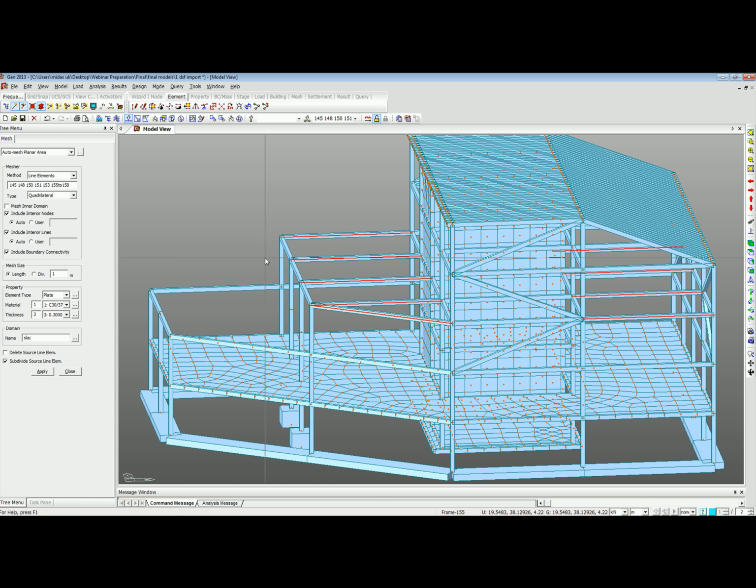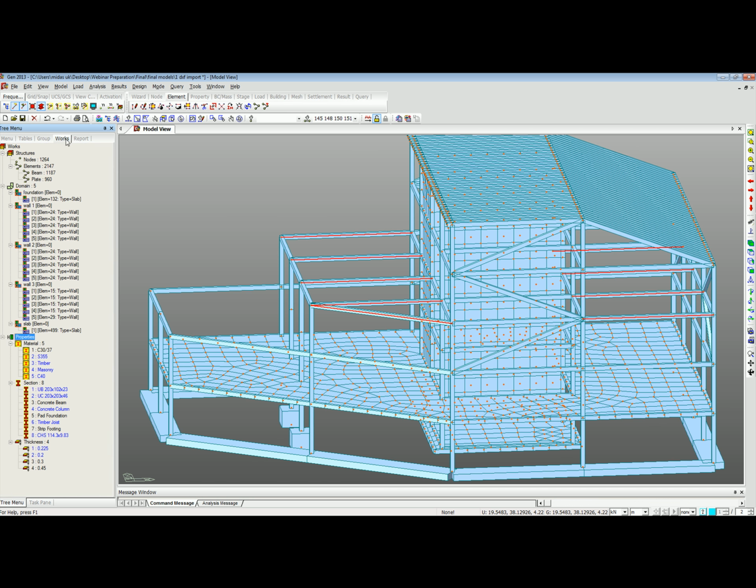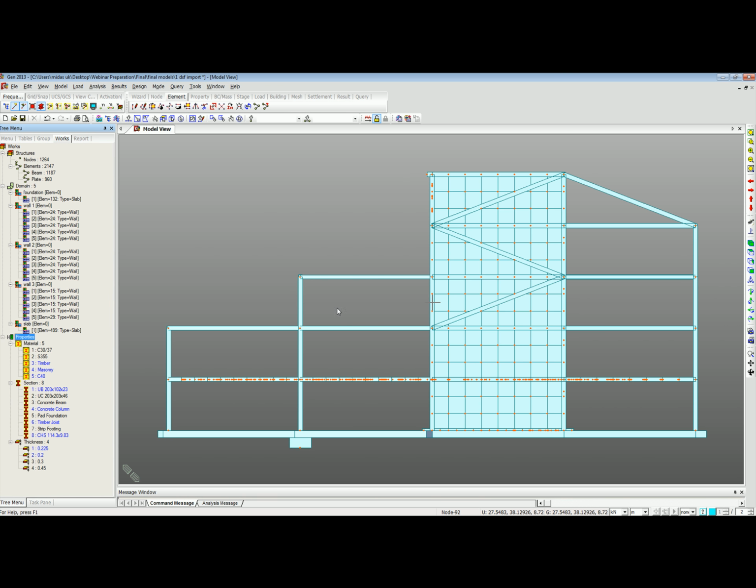So in this case we're going to have some steel beams. Let me select those. Back to the material section database, and I can quickly drag and drop them in, and that's that updated. Again, I could do that for the bracings, the columns, etc. They're all available. I need a few other walls in here, a few other slabs in here as well. So let me make them concrete as well, and put in the other columns.